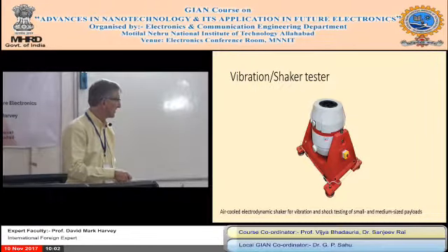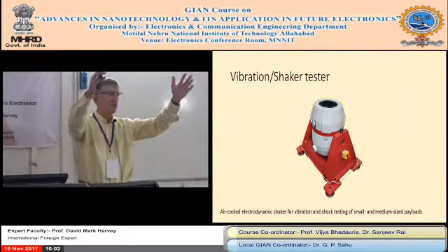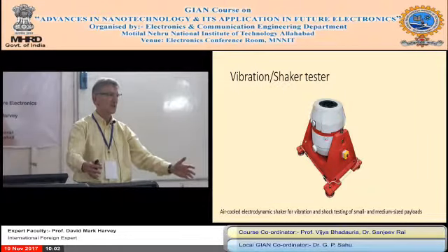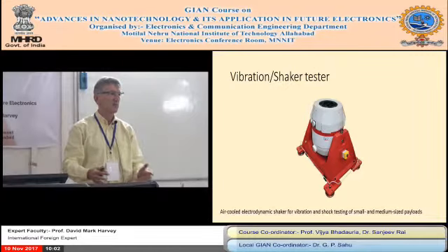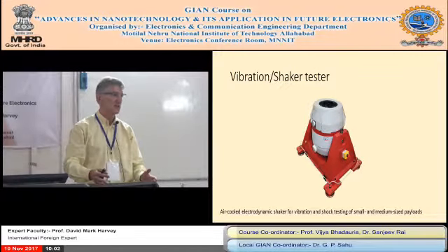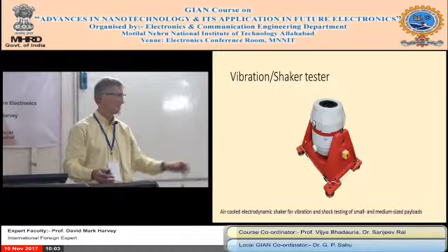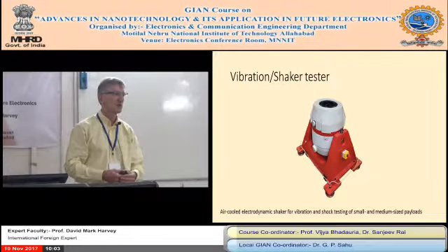On top of this, on the big ones, you sometimes have a thermal chamber that drops down like a big oven on top. So you can do vibration and temperature cycling at the same time. We call it mixed environmental testing. And if you've got enough equipment, you can spray water at it as well, but that would be quite difficult because you don't want the water to go into this machinery.